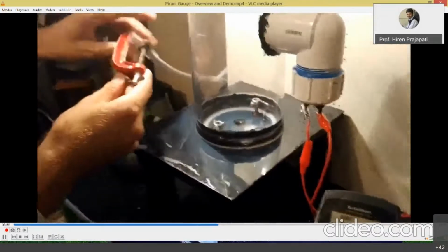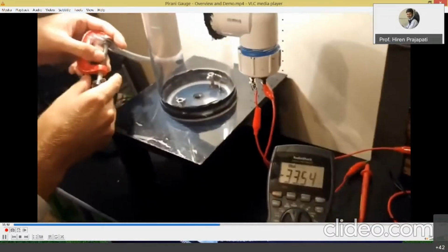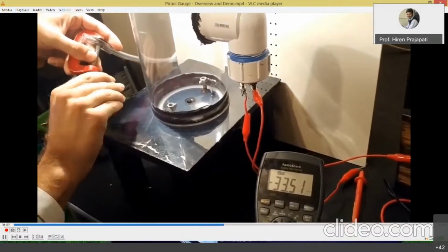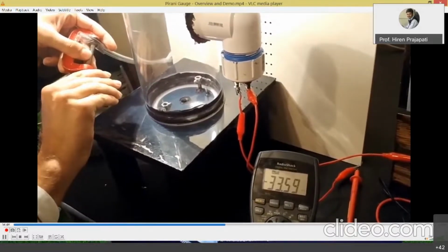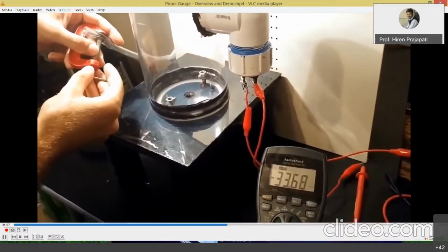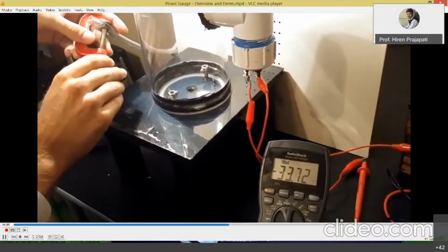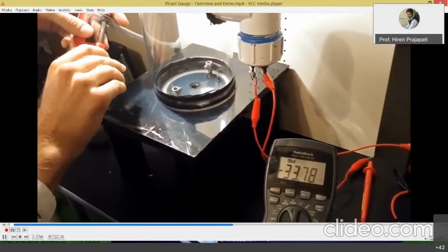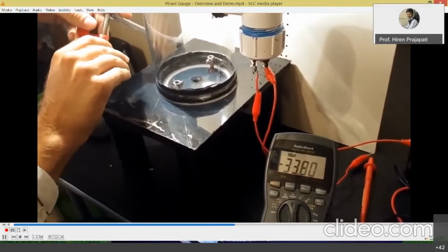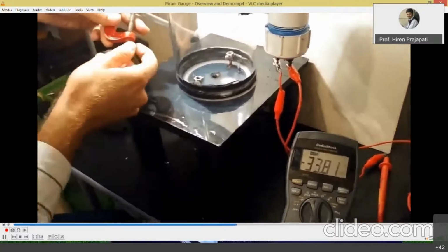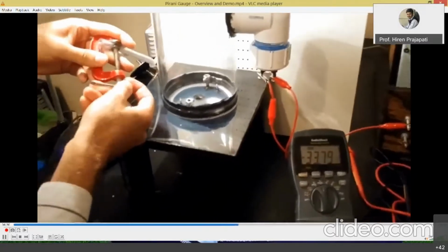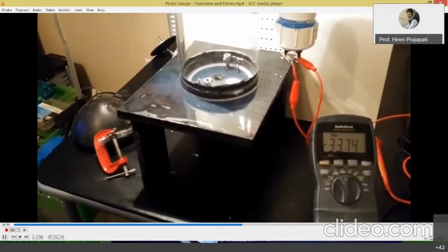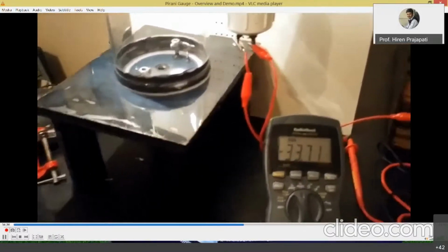Okay, now going to crack the air inlet slightly and observe the reading. Now you can hear the pump sucking air a little bit. See that reading start to rise as the pressure rises. And that's only a very small change in pressure, because this gauge is extremely accurate, with extremely fine resolution in low pressure environments. Now I close it back down. Now we can watch the pressure steadily return to the minimum that it was at before.